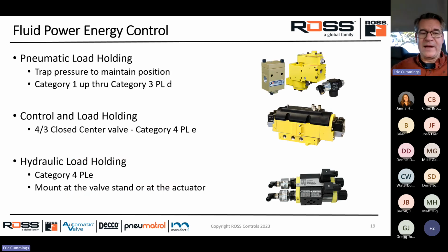There's quite simply pneumatic load holding valves. Typically, we call these a pilot operated check valve. So technically, we're going to exhaust the air from the valves that are going to those actuators, but we're going to trap pressure on those cylinders that we want to stay in place that could create hazardous motion. It's a pretty common device that's used in machinery these days.